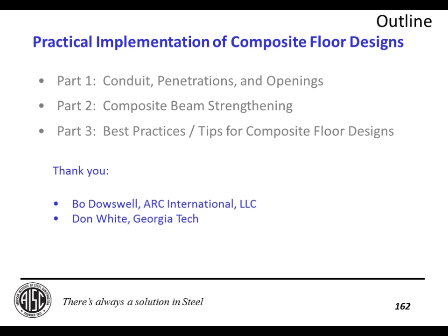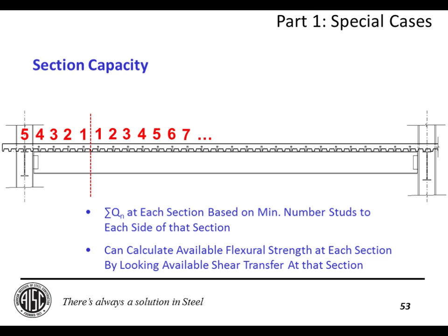So for our first question, I'm going to take us back to slide 53. The question is, can you use the stud on the girder when computing the sectional capacity? No. I believe they're referring to this stud there. Yeah. No, I should not have. You should be using the stud on the beam.